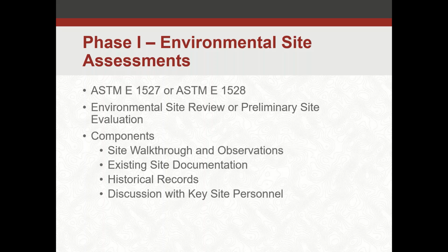Discussion with key site personnel is another beneficial step to go through during this process. If you've had someone that's managed a property for several years, they're vital to identifying things that you may not know or see during your site visit, and that can definitely go a long way. Maybe there are some materials in a wall cavity that you can't see, or a ceiling cavity that you can't access, and they can give you information details for that, or they can give you information on past abatement or remediation projects and how far those went, and maybe things that might have been left behind that still need to be addressed.